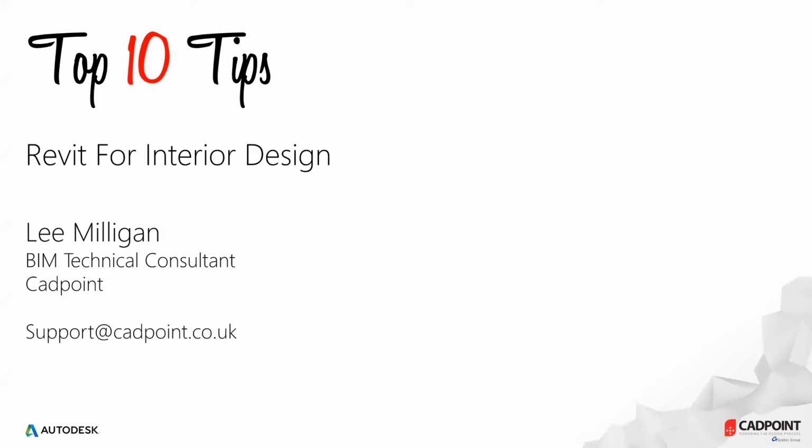The key point there though is not changing it down the bottom where I was showing it, but in the visibility graphic override. So once you have your different design options set, you can go to the visibility graphic overrides, and you can change it in there. Perfect. So again, just let us know if you're having any specific problems with that, or with what Lee's just said, and we can try and help you around that.